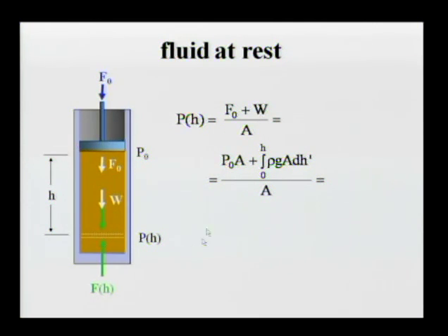Now, in order to find weight, I will have to divide this entire fluid into slices. For each slice, the cross-sectional area times the height of the slice gives me the volume of the slice. If I multiply by the density of the fluid, I get the mass, and multiplying by acceleration due to gravity gives me the weight of the slice. Then I add it up throughout the entire depth, which gives me the weight of that fluid. Why do I integrate rather than multiply the density of the fluid by the volume of that fluid? Because I don't know if that fluid is uniform, correct?